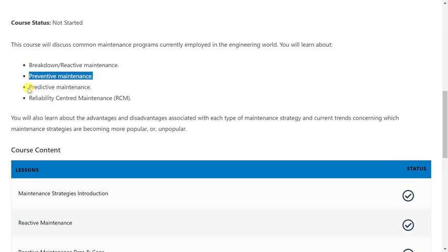So that's preventive maintenance. Predictive maintenance is where we try and predict when failure will occur. Now we can do that by measuring things such as the temperature, pressure, level of vibration, ultrasonic tests, non-destructive testing, etc. We'll get into that in more detail later on. It's a very exciting field that's come through a lot in the past 10 years, and it's now beginning to dominate many plant maintenance strategies.